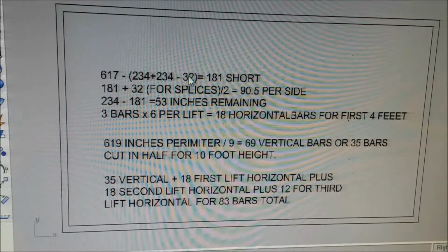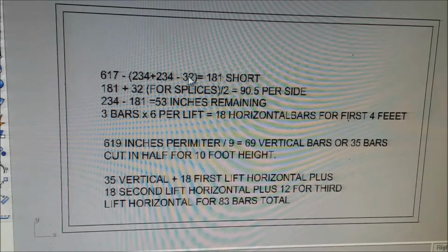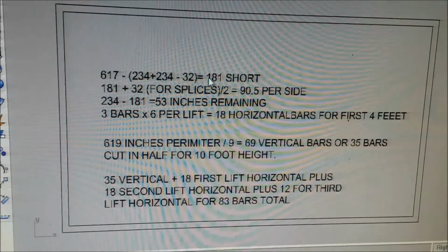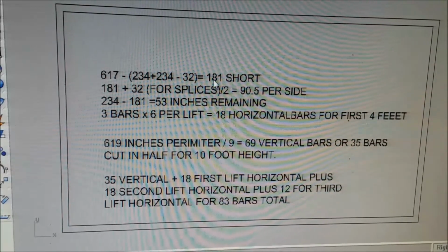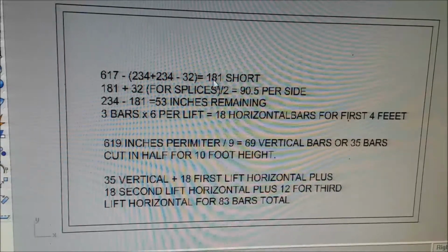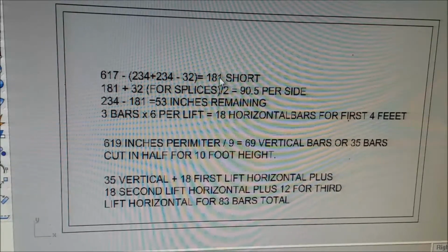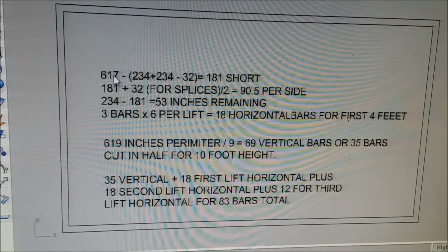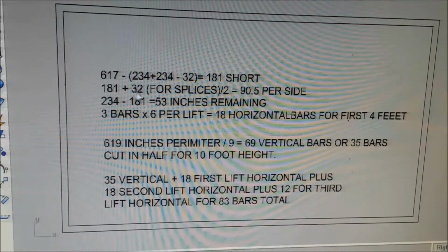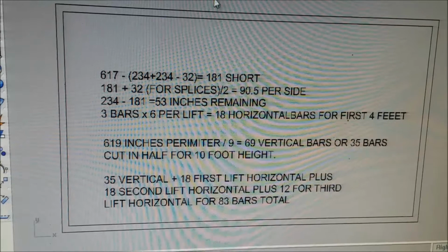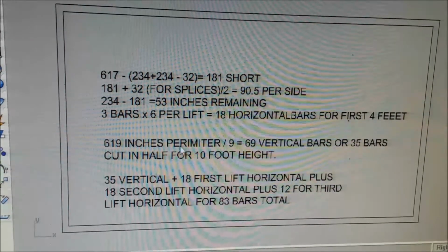So we're going to subtract off a splice length, and that's going to leave us a leftover of 181, and that's going to be made from another bar. And because it's going to be spliced onto these other two, it's going to need 2 more 16s, one for each end of the one over here someplace and one at the bottom someplace.